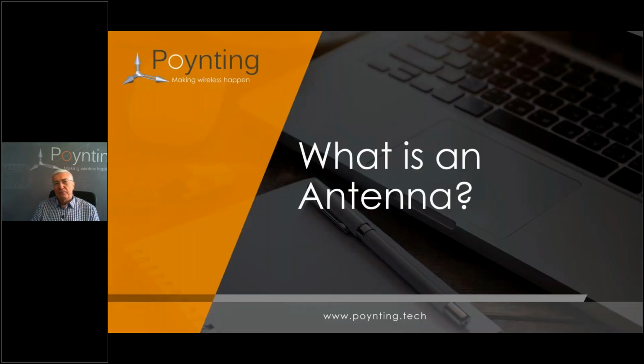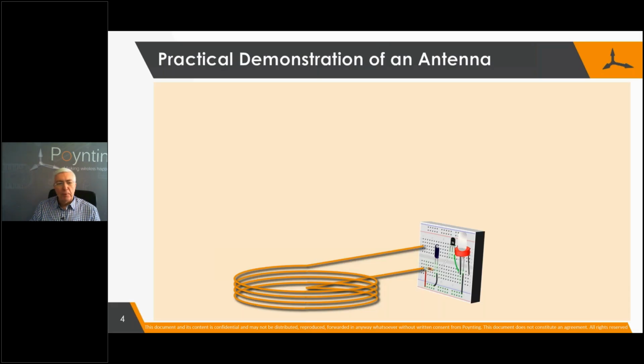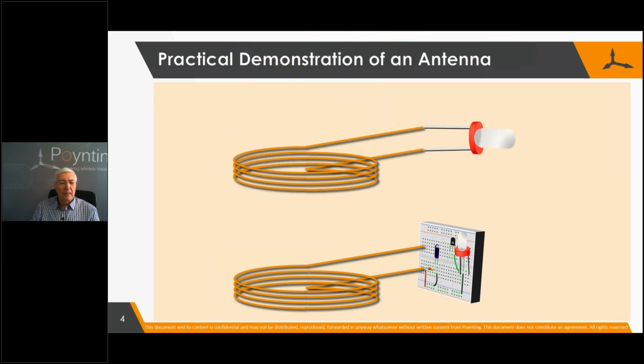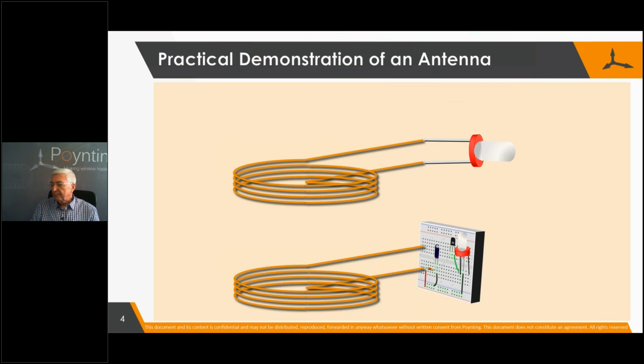Right, so let's first look what is an antenna. I'm going to show you a little practical demonstration. I've shot a video in my RF lab, and that is going to consist of a transmitting antenna with a little oscillator that creates an electromagnetic wave. We'll have a receiving antenna. That receiving antenna is going to, as we switch on the oscillator, get an electromagnetic field induced in it, and you'll see that little LED that shows us the current that's being induced lighting up.